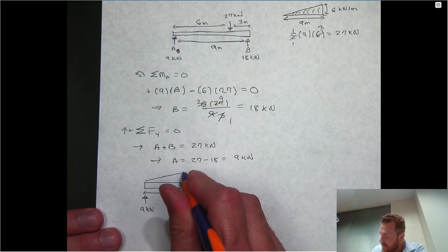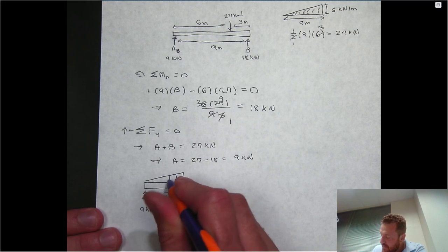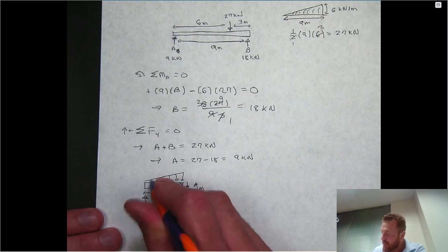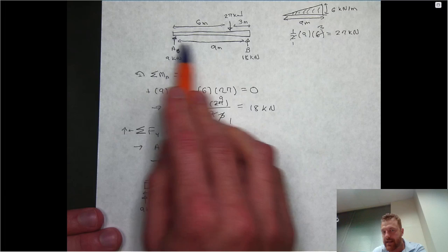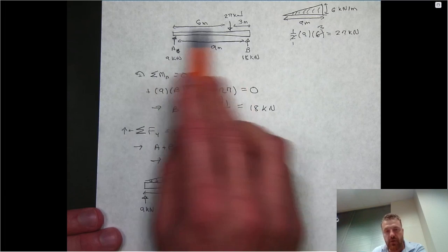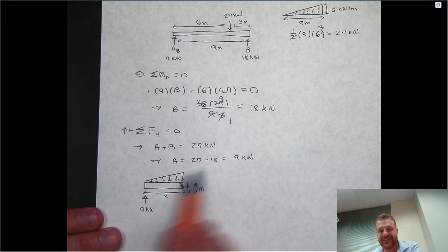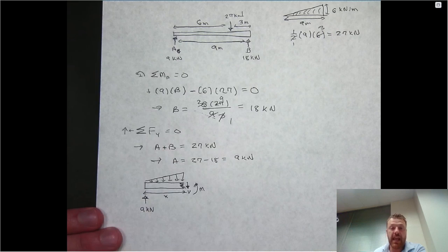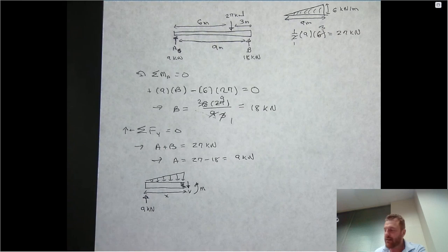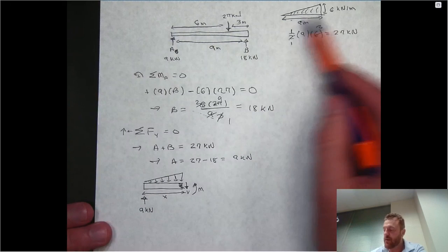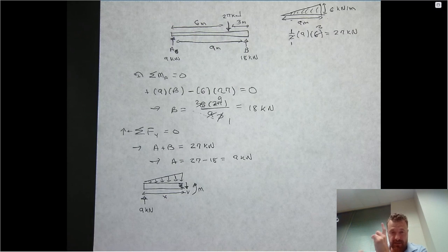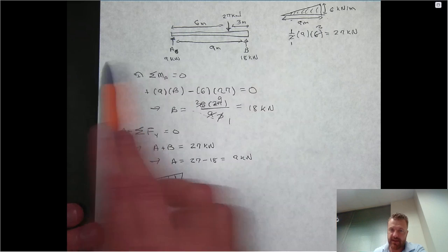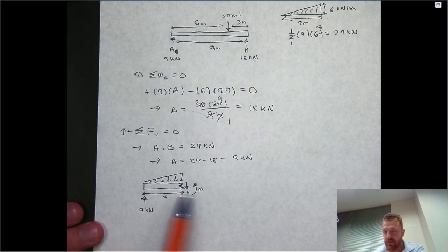And that's one of the challenging things that people struggle with sometimes, because they look back at the original free body diagram that we used to solve for the reactions, and they say, hey, at some arbitrary x before I get to 6 meters, there's no force applied. But remember that distributed load is actually subjected across the entire beam. And when we originally talked about the idea of replacing a distributed load by a single concentrated force, we said that that was only valid for determining external forces like reactions. So when we want to determine these internal forces, we have to again consider it as distributed.